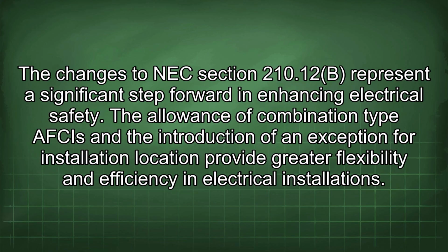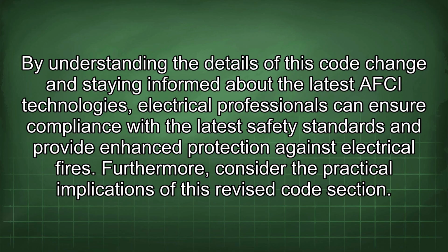The changes to NEC Section 210.12b represent a significant step forward in enhancing electrical safety. The allowance of combination type AFCIs and the introduction of an exception for installation location provide greater flexibility and efficiency in electrical installations. By understanding the details of this code change and staying informed about the latest AFCI technologies, electrical professionals can ensure compliance with the latest safety standards and provide enhanced protection against electrical fires.